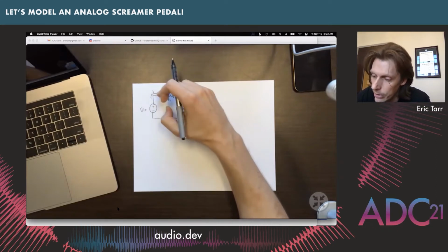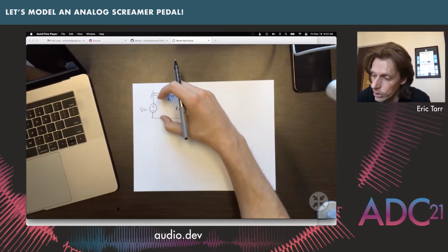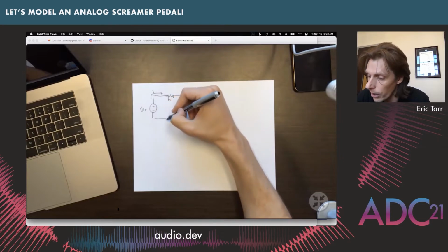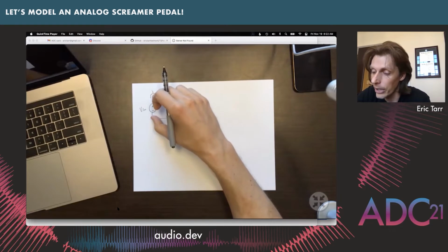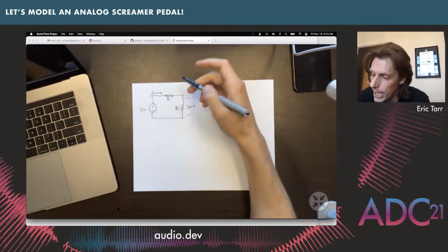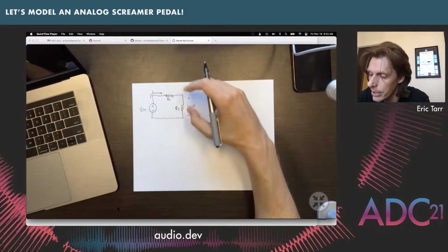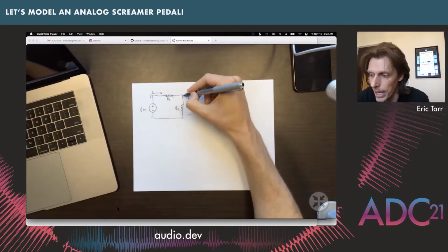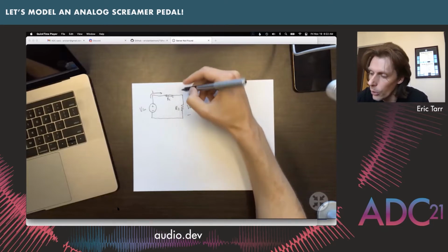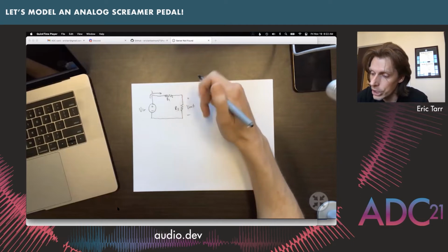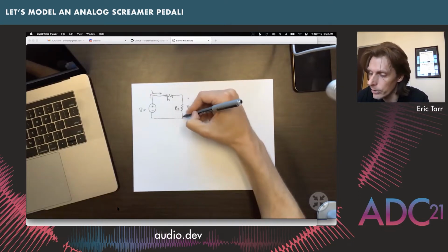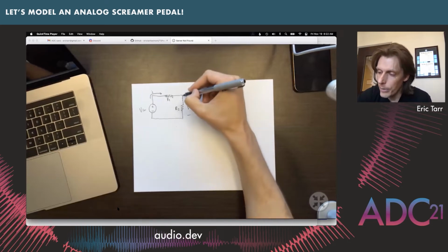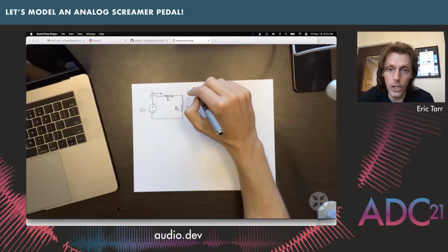And we're taking the voltage down to this other wire somewhere along here as the thing that is defining our input voltage. But we have a different voltage that occurs over here because it's split up by these resistors. And so we're going to take some measurement of the voltage that goes from this point down to this one right here. These points that we have in our circuit, we can call nodes.